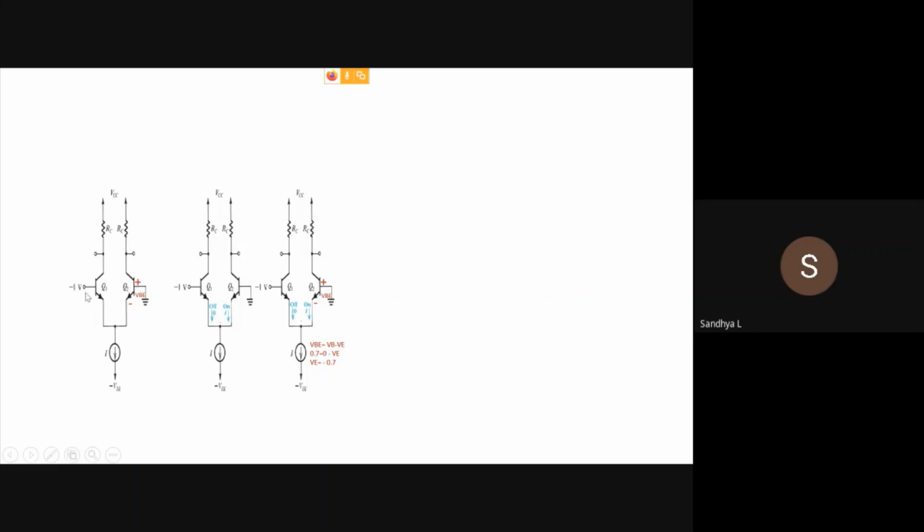So what is VBE of Q1? Minus 1 minus of minus 0.7. So minus 1 plus 0.7. So that is minus 0.3.